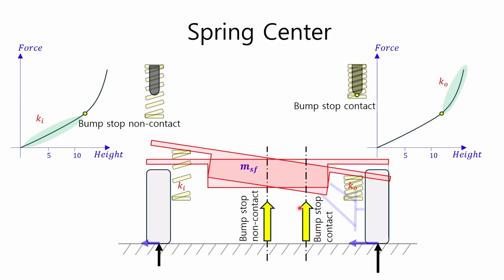When the bump stop operates, the role of the shock absorber is significantly reduced, and the force input to the tire goes directly to the car body through the suspension links and bump stop without going through the shock absorber. This can cause problems with the durability of the tires and body, as both the tires and body have to absorb the force that the shock absorber should absorb.